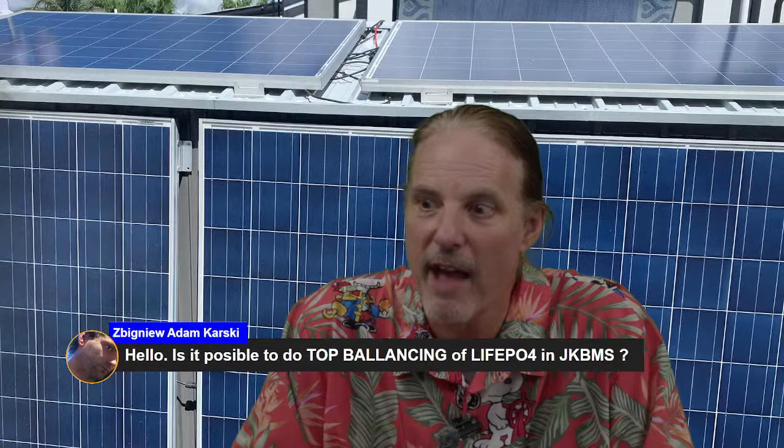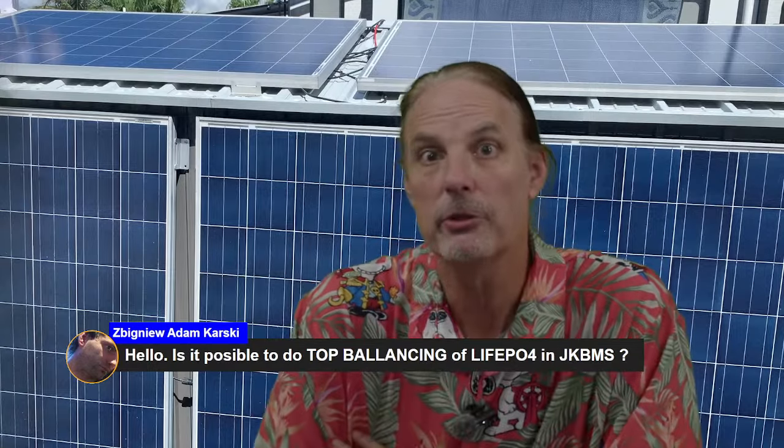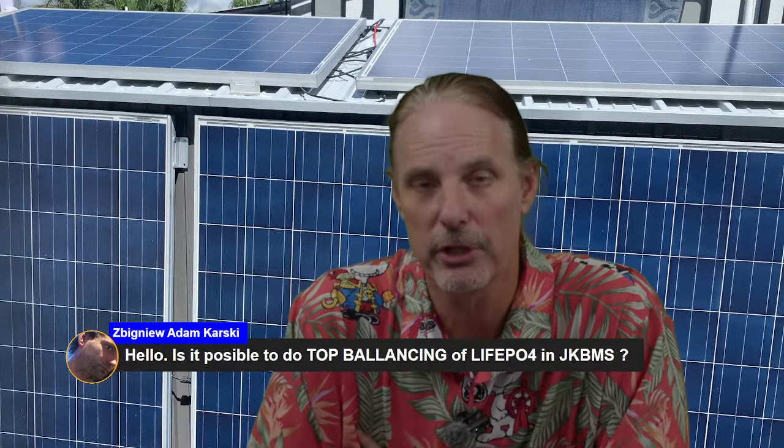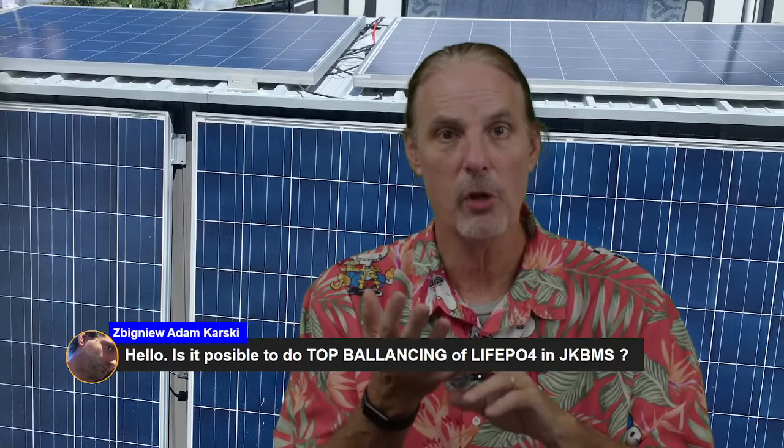I don't know that I have a video out on it yet, but actually I do. The DIY battery building video that I put out earlier this week does go into the JK BMS and how it's configured. Basically you set the cell minimum voltage for it to start, which in my case is 3.4 volts.